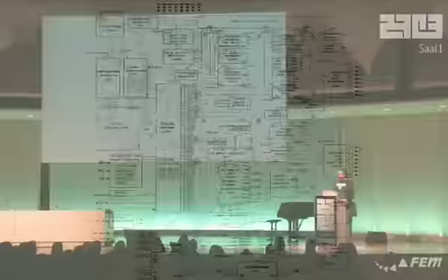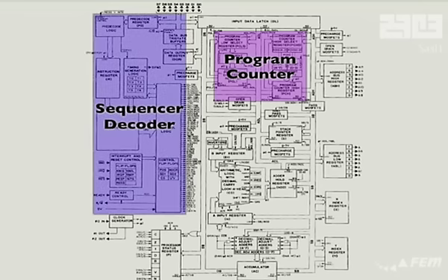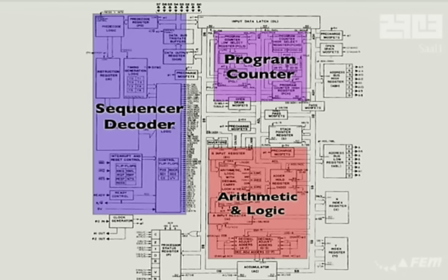For everything here, we have to start with this really nice schematic diagram again. Let's look at it in a little more detail now. Program counter, that's not all that interesting. Sequencer and decoder, this is where the actual personality of the 6502 comes from. The rest is pretty standard. The whole arithmetic and logic is done like in any other CPU. You have the registers here, and the stack pointer, and the status register again. And the two buses, so the S bus on the left is connected more to A and the ALU, and the other bus is more connected to the indexing part of the system.